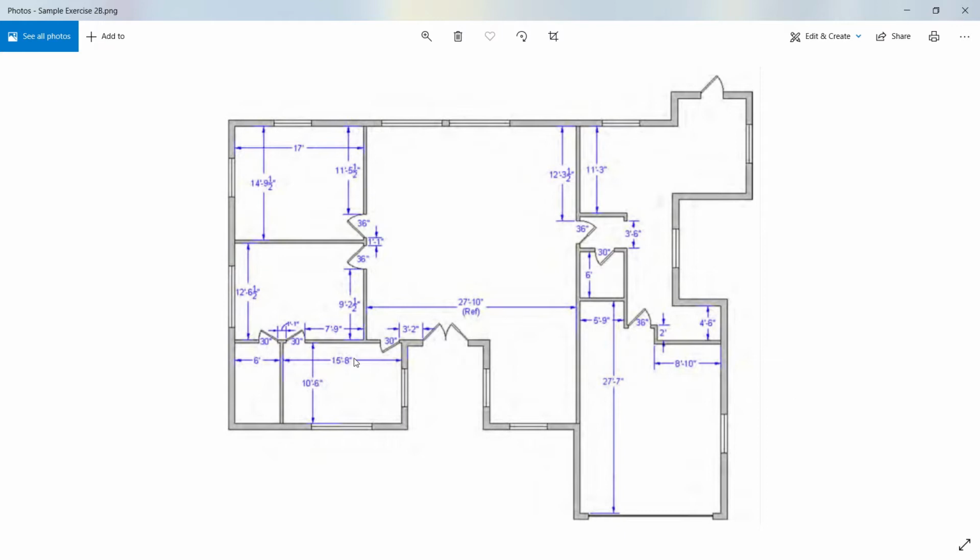you should notice here, and the doors are rotated 30 degrees, and the opening for each door, like for example the bedrooms, okay, the thickness of them is 2 inches for this particular sample exercise. And also this is the garage door, so it will fall under the door layer. And then you will be creating additional layers for this particular sample exercise.